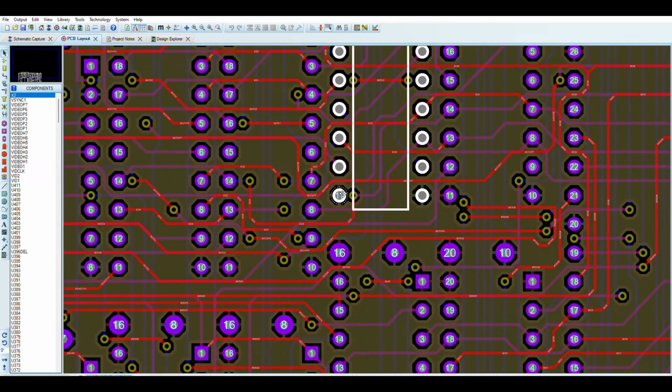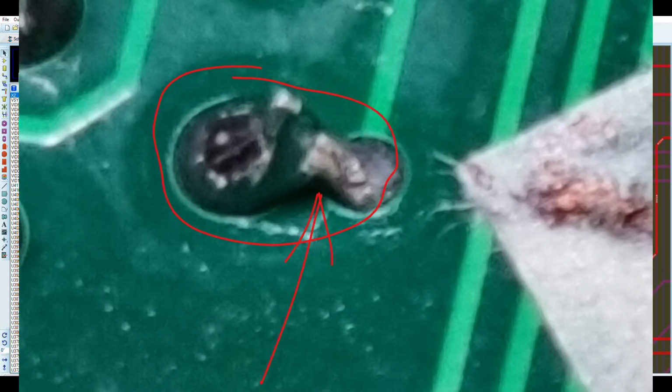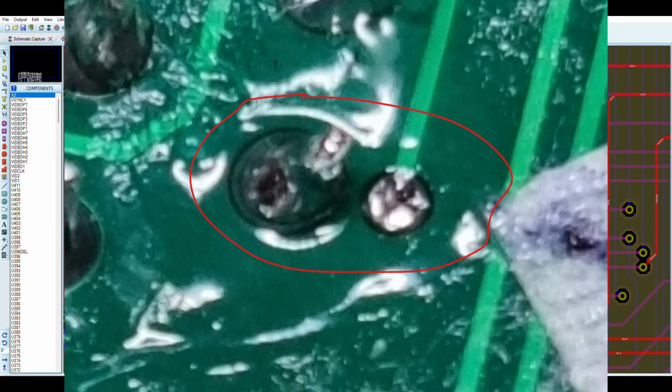Pin 11 is usually set to, as we can see down at the bottom here, VCC on the power net. And next to it there's a wire which is connected to net ED5. The solder bridge was across here, basically. The before picture and the after picture shows how the repair looked.